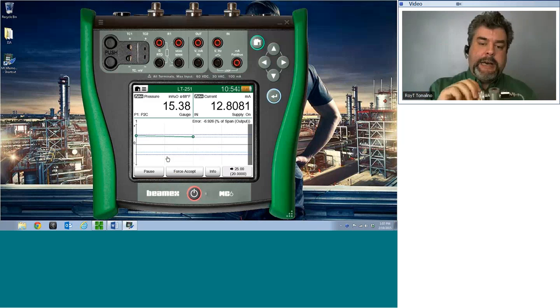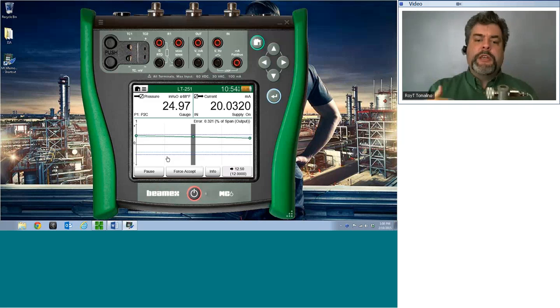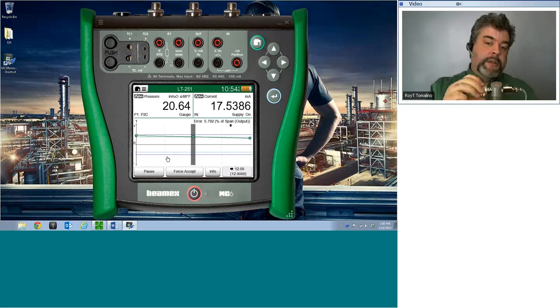So there's two ways to do a calibration. One is either it passes or it fails. And if it passes, you don't make an adjustment regardless of how close it is to being out of tolerance. And in this example, we're saying if the test results are within 75% of 0, then don't touch it. But if it's outside of that, then make an adjustment.